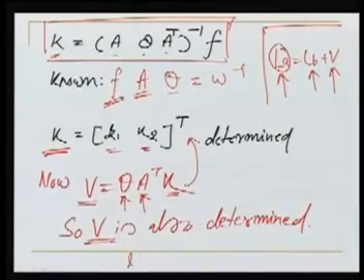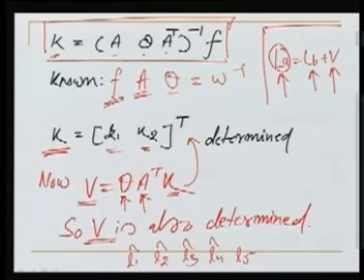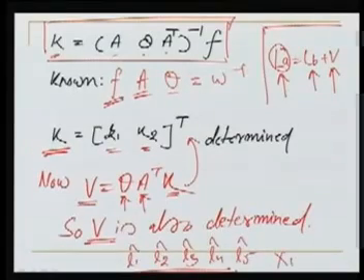Once we had these adjusted observations in this particular problem, we now know L1 hat, L2 hat, L3 hat, L4 hat, L5 hat. All these are known to us now. If these are known, I can simply find the value of x1 as benchmark plus L1 hat.